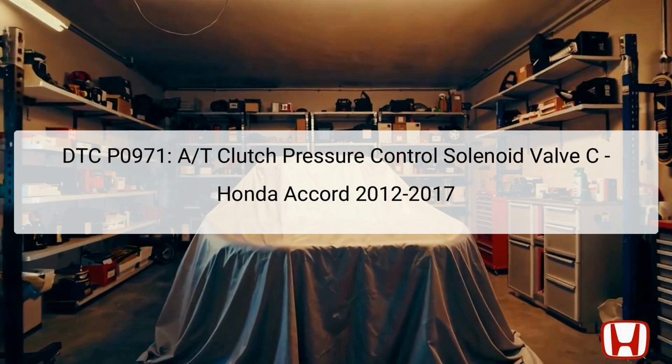DTC P0971 refers to a fault in the AT clutch pressure control solenoid valve C within the Honda Accord models from 2012 to 2017. This solenoid valve plays a crucial role in regulating the hydraulic pressure required for the automatic transmission to function correctly. It controls the pressure applied to the clutches, which enables smooth gear shifts.